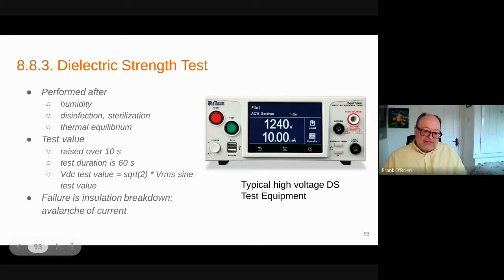So you set it at kind of the lowest that would give you nuisance trips for the safety of the tester, the person testing. All right, so this special test equipment on the production side, you'd buy the ones that are programmable with leakage and data logging, whatever else you might think is good.